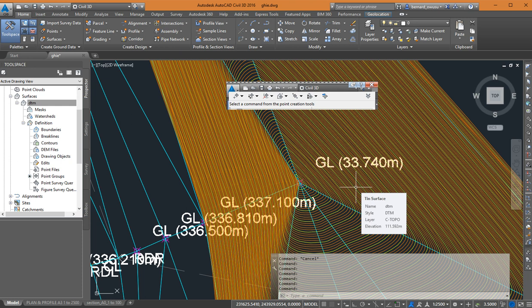I'm saying that AutoCAD Civil 3D has this facility whereby you can have a range. You can have a minimum value or a maximum value, below or above which it will ignore the elevations. So we are going to tell AutoCAD Civil 3D. That is why it is good that you also visit the site to have an idea of the terrain. Now this particular area is towards Mampong area. That's why you have elevations in the ranges of 300.